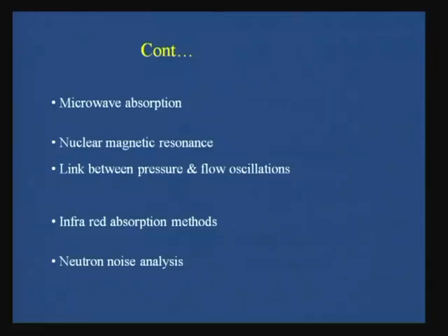Instead of gamma rays we can go for infrared absorption techniques. Now, what is the beauty of this technique? Most of the techniques I have told you are very good for water continuous systems or liquid continuous systems. For high quality flows, most of them do not work well, because the absorption or attenuation of radiations is maximum for water and much less for air. So, when there is a large amount of air, whatever small water amount is there does not much affect the attenuation process.